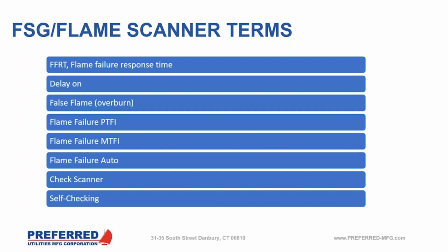So again, this is giving us another tool also to see what's going on. This could be caused by a variety of issues, including maybe a flame scanner is starting to fail. It could be a temperature related problem. So we just don't know. But this again tells us in that startup procedure and running sequence, if you will, when we lost the flame signal.